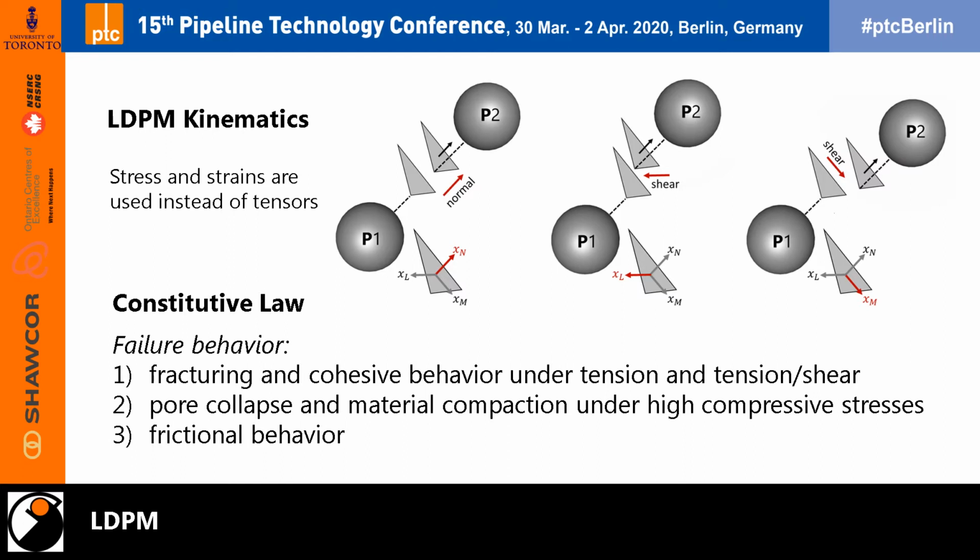And the fracture behavior is calculated from the constitutive law, which has three subcategories. The first is the fracturing and cohesive behavior under tension and tension to shear. The second is the pore collapse and material compaction under high compressive stress. And the third is the frictional behavior.